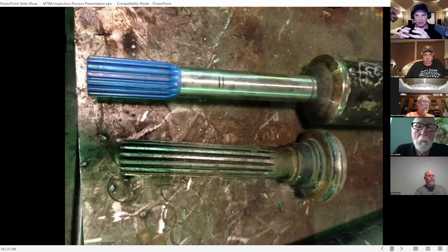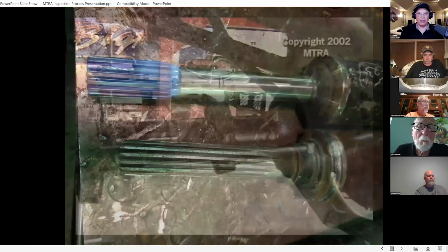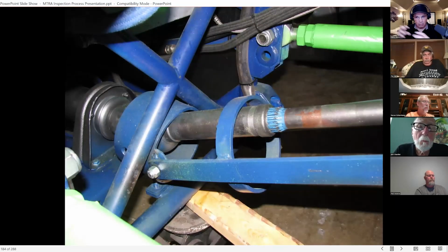The other critical issue is in situations where you have them pulled out very far. There's a bit of tolerance between the engagement of the splines, so the further out you have them, the more they tend to oscillate and rock, and that can cause the drive shaft to fail. So it's not necessarily just the fact that the drive shaft is going to pull apart. It's creating a situation where you could have a failure strictly because you don't have enough engagement.